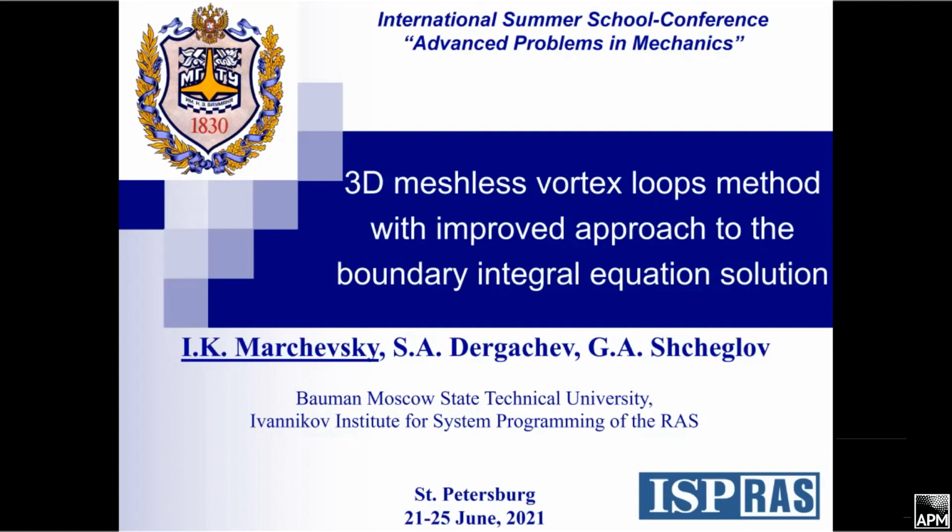In the first problem, we consider the airfoil moving horizontally in still media. In the second problem, we consider it moving vertically in still media. And in the third problem, this is rotational motion, again in still media. Having the solutions of these three problems, it is possible to compute all the components of the tensor of added masses. But as far as I remember, for the added mass tensor, it is necessary to have accelerated flow, and not steady state.